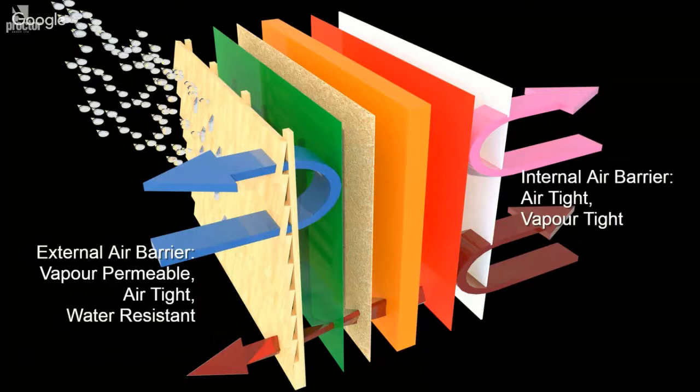However, there are more advanced membranes today, some which have self-adhered characteristics, which allows for a more continuous external air barrier whilst remaining breathable. When using membranes of this type, it's really important that vapour control is very carefully considered. It might be necessary to limit moisture vapour transfer, for example, using a well-sealed vapour-tight insulation board.